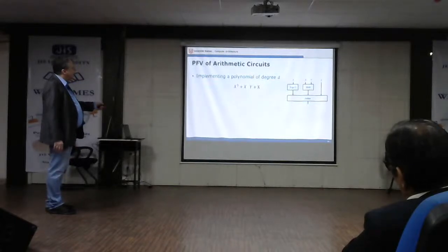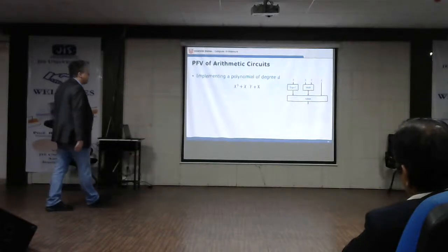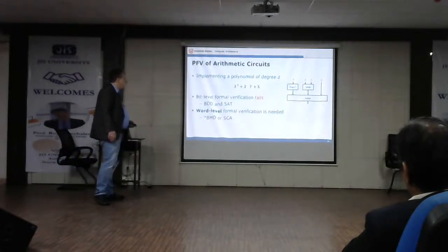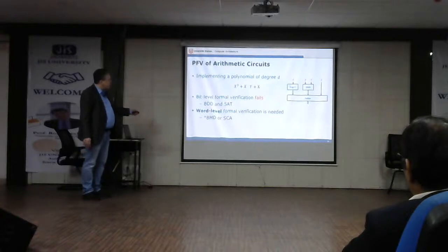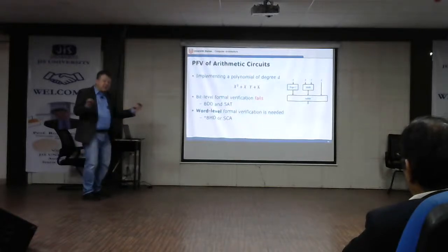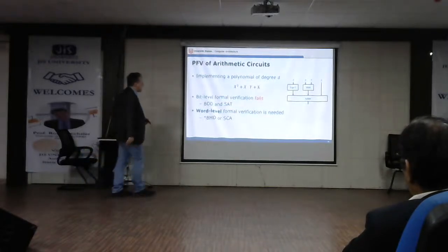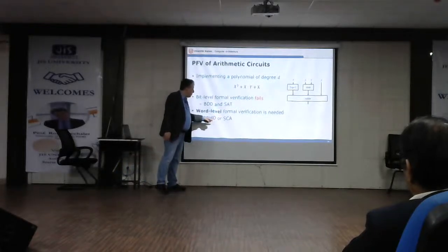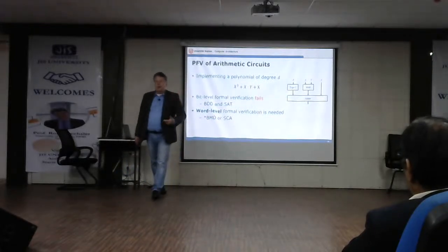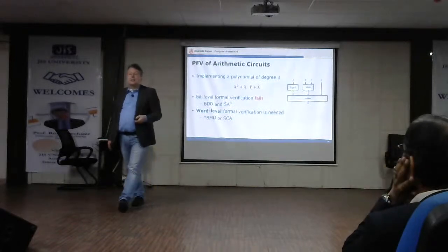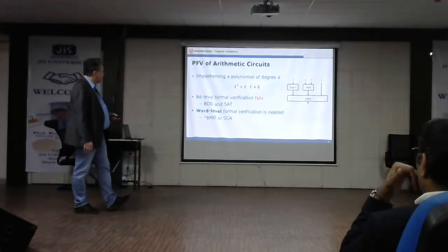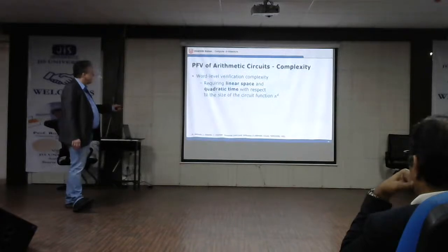Also some more ideas when you implement polynomials, like here where x and y are some kind of larger scale polynomials. It's also the case that BDD techniques, these bit level techniques, will fail, but there are some word level operations. Yes, we can also include word level proof techniques in these engines. They can handle these and can work with them efficiently.